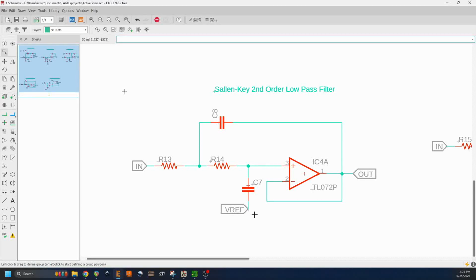Because with a single pole filter, a single order filter, it is a very basic, well-defined thing. But once you get into higher order filters, you can start specifying things like overshoot of a filter, which is how far beyond your desired response it ends up going in time.